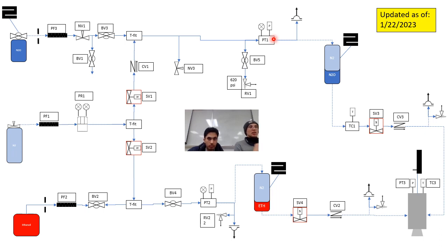If it's below 600 or if it's below 580, again, subject to change based on some of the details, we'll use our closed loop control to activate SV1 to just top off that pressure. Hopefully that's not happening too often. We don't want to just lose nitrogen all the time. We don't want to just leak this whole time. But if it does happen, we definitely want to just keep it pressurized until we make a conscious decision to vent or to launch and start that ignition process. Final automated check of all the instrumentation, and then we begin the ignition process.